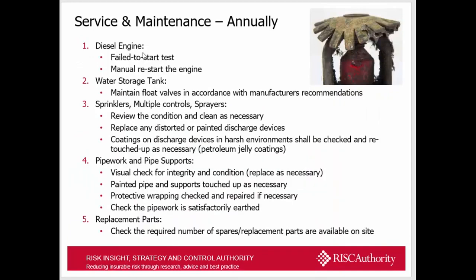So moving on to annual. There are quite a few checks to be done annually. So on the diesel engine, you've got a fail to start test and manual restart of the engine. Water storage tank, maintain the float valves in accordance with the manufacturer's recommendation.